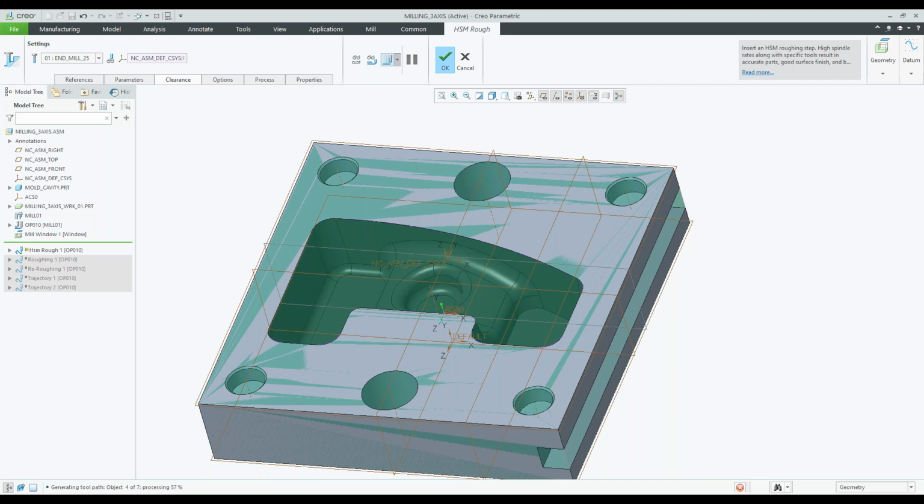We had a question about the shrinkage that's been added. So yes, if you use the mold manufacturing license, there's shrinkage that you can add to your components, and then you will add the shrinkage before you subtract it from a billet or from a die plate or something like that.